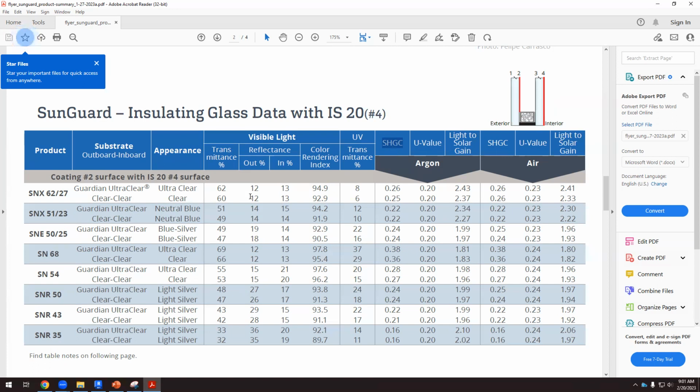And it's not only double glazing or triple glazing, it's the coatings. You see all these coatings, which are thin layers added to the glass itself. They can be transparent or not as transparent, but they can deal with the solar heat gain coefficient and the visible light transmittance.